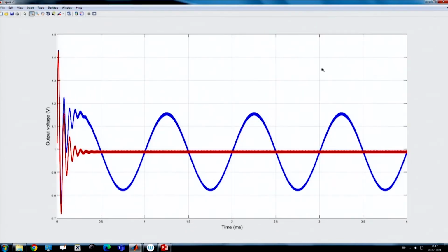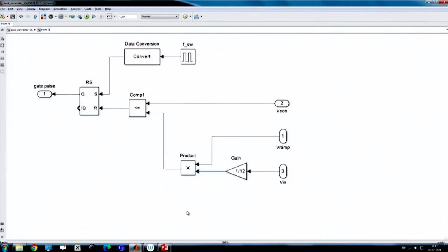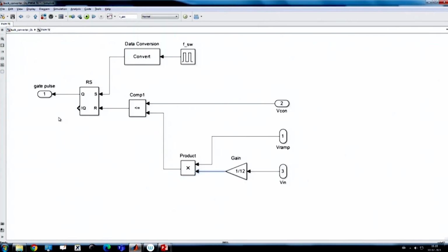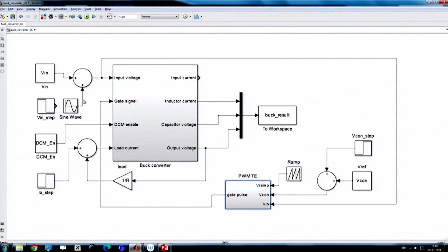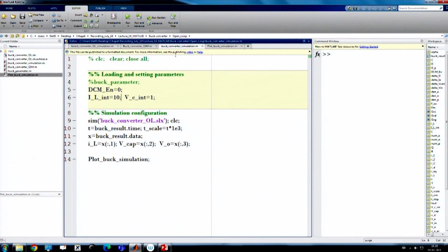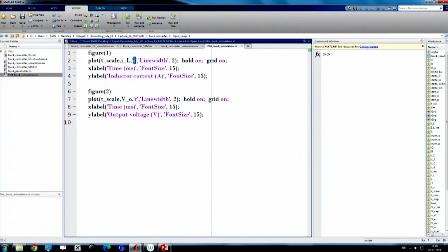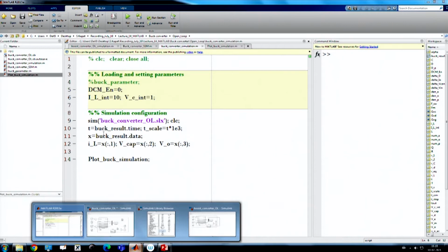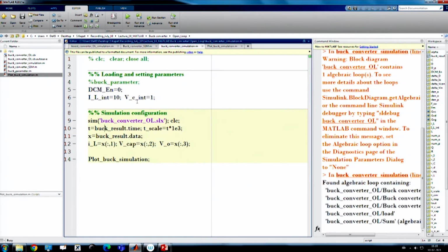We want to see what happened with our original one when we considered the step transient. So now go back to our simulation, and we want to remove this sinusoidal excitation, connect back our step transient and rerun this simulation. In this case, initially we want to plot this with feed forward action, and then we want to see without feed forward action.